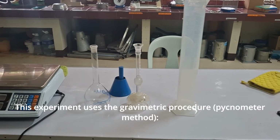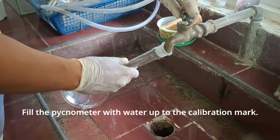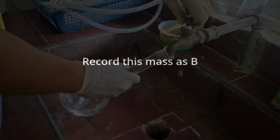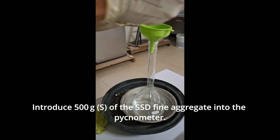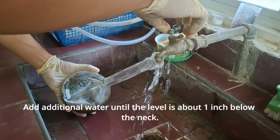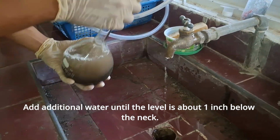Gravimetric procedure using a pycnometer. This experiment uses the gravimetric procedure or pycnometer method. First, fill the pycnometer with water up to the calibration mark. Record this mass as B. Next, pour out approximately half of the water. Then introduce 500 grams of the SSD fine aggregate into the pycnometer. Then, add additional water until the level is about 1 inch below the neck.